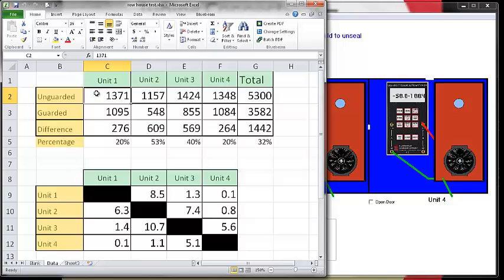So we can see our 2 outside units changed by about 20%, and our inside units, where they're connected now on both sides, changed by about twice that. And the total, if we add all those numbers together, it's about 32% leakier total leakage compared to leakage to the outside. So pretty dramatic differences.